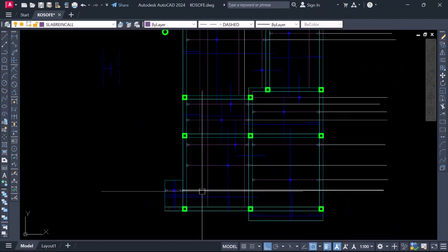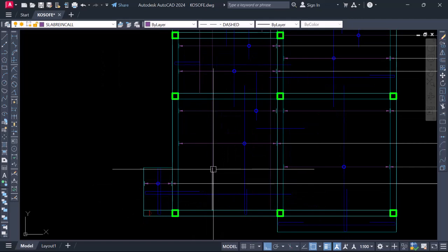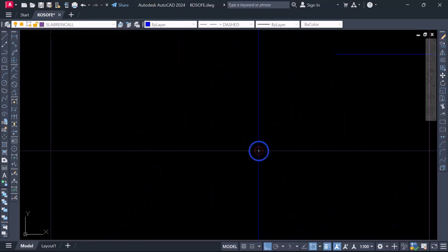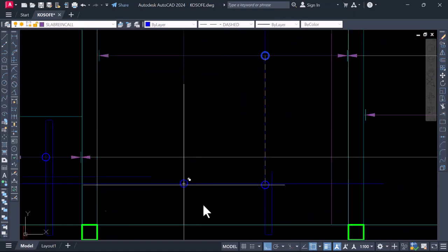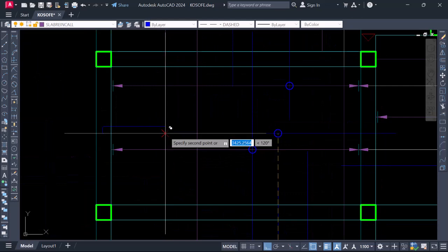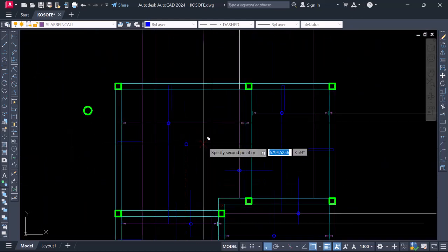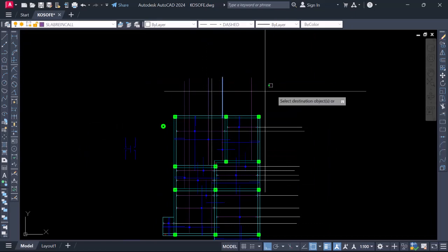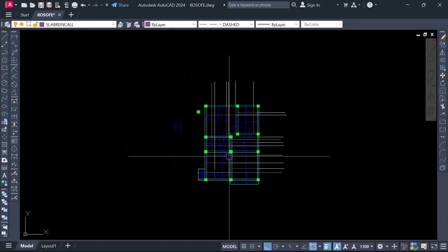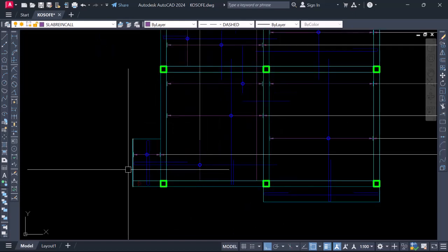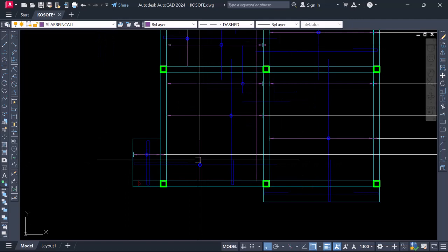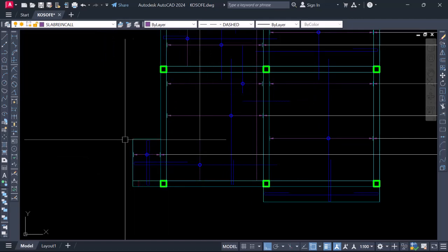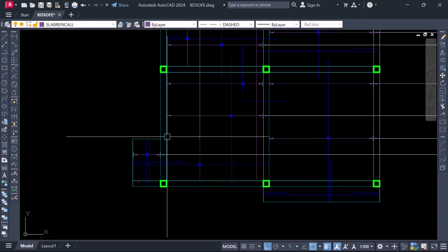So in this direction, looking at this span, we've identified the span. Let's start tracing so that we won't get confused. That is it for this panel and also for this panel. Let's copy the property, let's match property for all the directions. You can see that we want this reinforcement to run in this direction, from here and end at this panel, where we have a terminating panel.